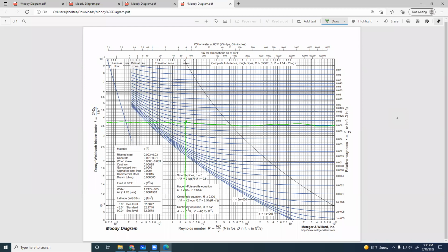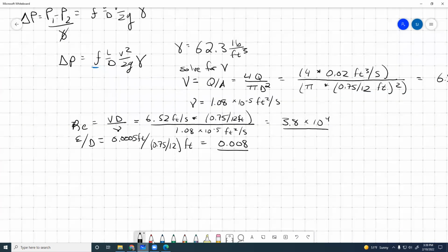Oh, okay, we made it. That's brutal. Okay, so this is 10 times 10 to the negative 2. So this is about 3.7 times 10 to the negative 2. That's our friction factor based on the Moody diagram. So it just went up a little bit. It would have been 3.6 if we were fully turbulent over here. All right, we good? So friction factor, 0.037.